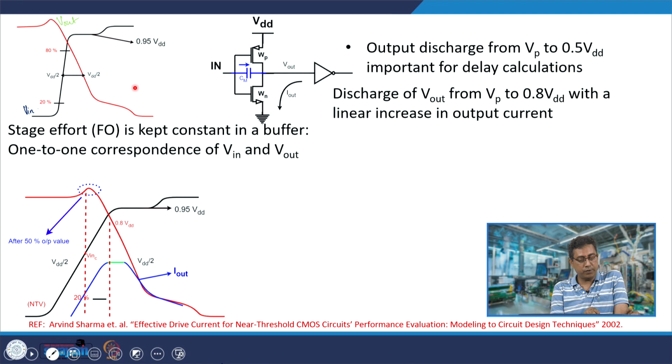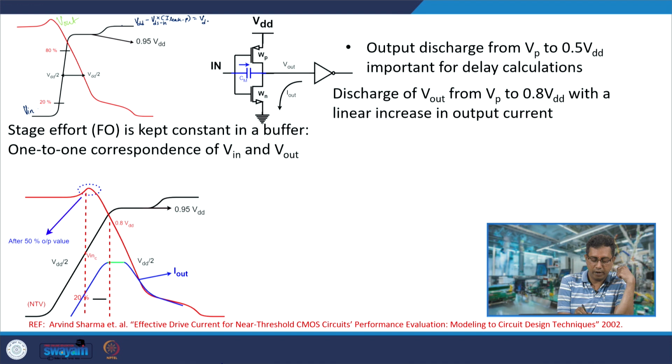So, when the input is VDD, there is a leakage current of the P MOSFET and I on by I off of the inverter is already not very large. So, therefore, we would find that this is not VDD, this value is VDD minus VDS of N MOSFET into I leakage of P MOSFET, as we had discussed earlier. So, this is like VDD static.